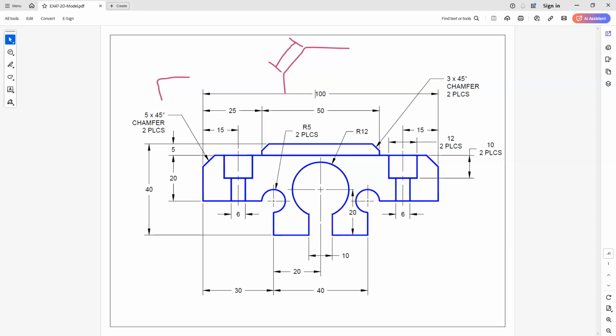This is one of the misconceptions that you'll run across in drafting. So if you look at this and you say, hey, that's what this means, you'll be incorrect. So just to make sure that I tell you, this is not correct, right? The true thing of what this is actually telling me is that, and I'm drawing this a little bit bad, but hopefully you get the idea, the chamfer distance goes from here, going up, and it says that this distance here going across is 5, right? And likewise, it's telling me also that here is 5.